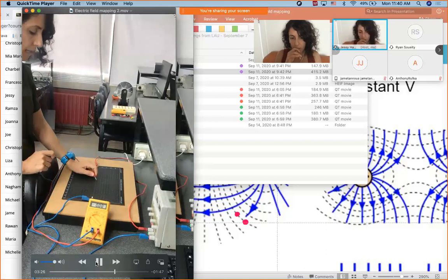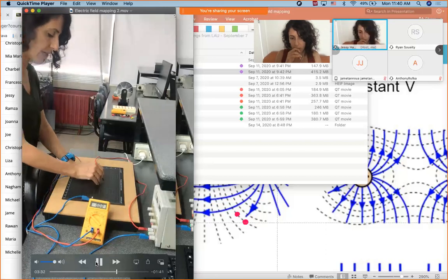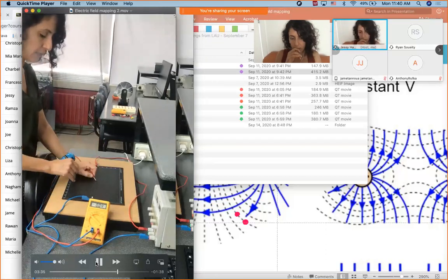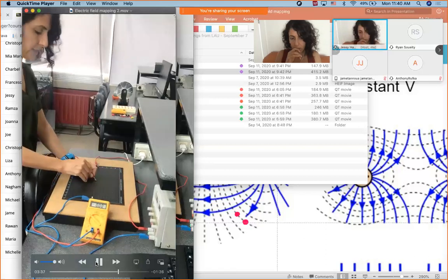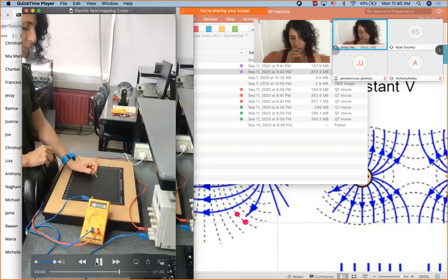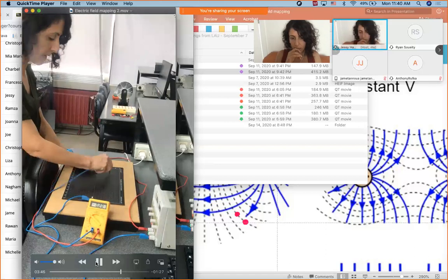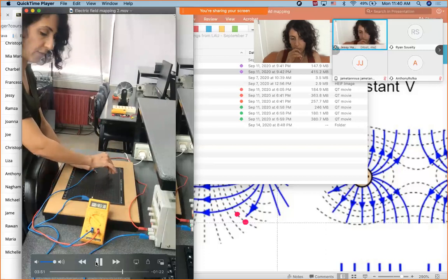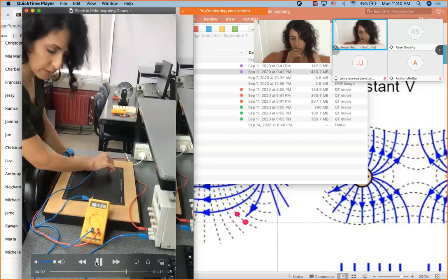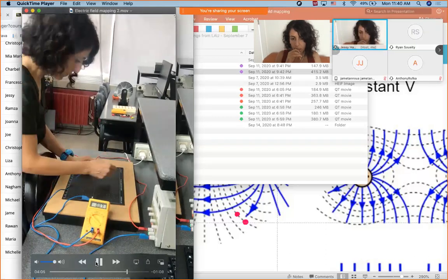Now I will actually move my reference 1 centimeter to the left and do the same thing again, trying to find my zeros, 1 centimeter up at a time. Move the reference until I get very close to the source, where I can see that a point just above the reference will not give you 0 at all. It will give you a value very far away from 0. This is where you're supposed to be moving your blue banana wire to the left and find the 0 that I'm not being able to find. Where is that 0? Okay, let me try again.